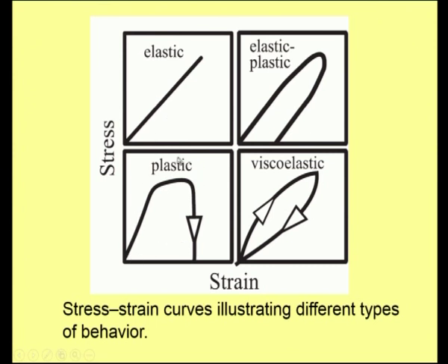Whereas in a purely plastic material, with the increase in stress, there will be a deformation, up to a maximum deformation, and then the flat region represents that with the increase in stress, there is no more appreciable increase in strain. Now once you release the stress, it will not go back like this. Instead it will take a path as shown. So this is the deformation which is permanently set in a plastic material, which is a typical property of metals.